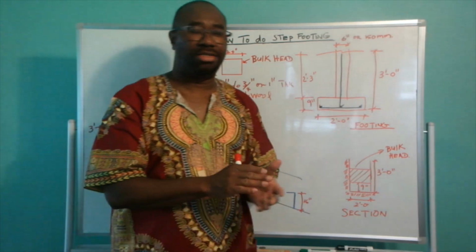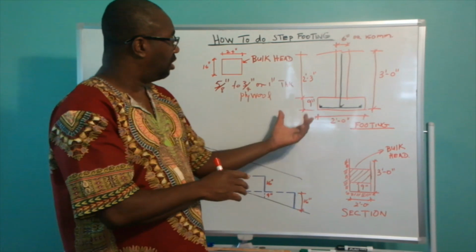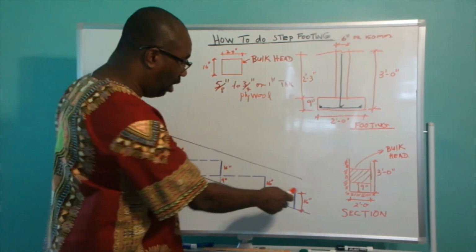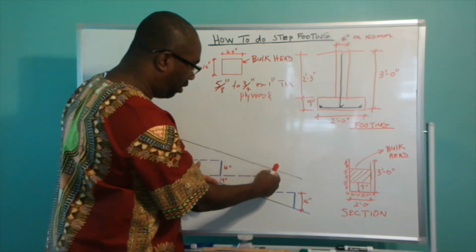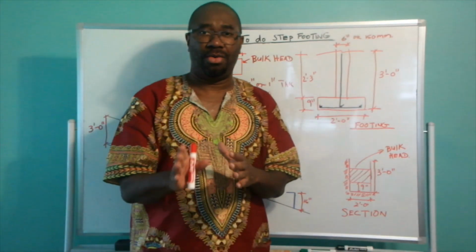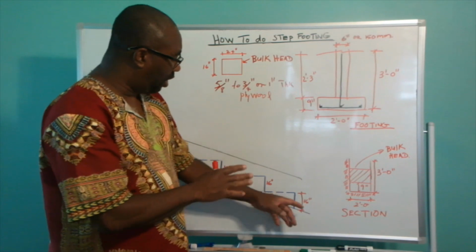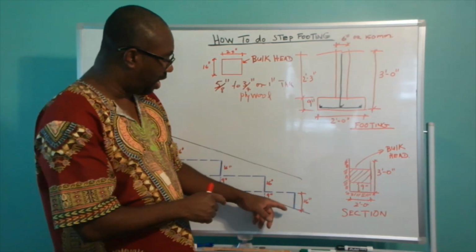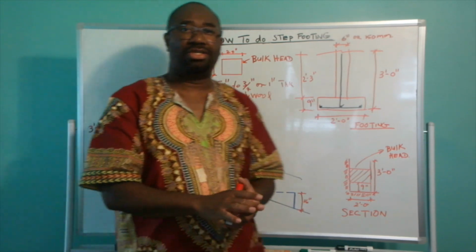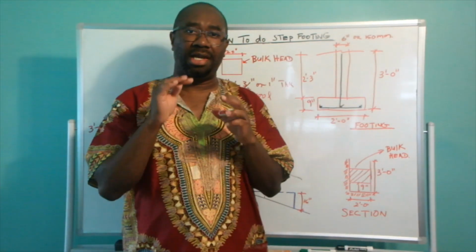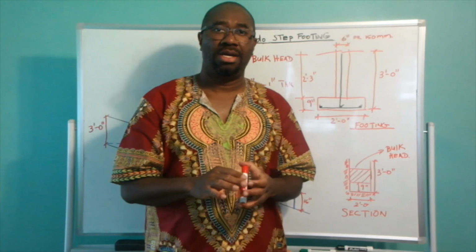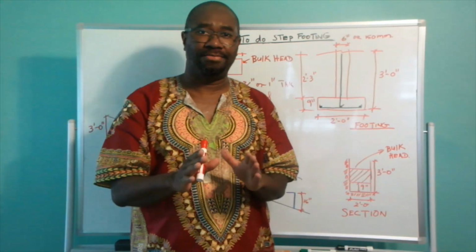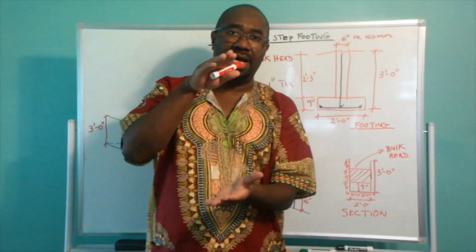So it is better to start out significantly higher than this 9 inches, and then when you level and get your 9 inches, that is where you step your foundation. And the reason why I've used 16 inches for my starting point is that you have to go up in increments of 8 inches, because the concrete block that you use on site is 8 inches high.